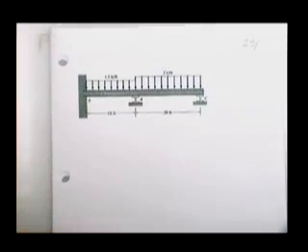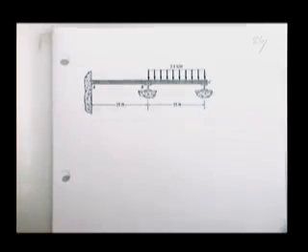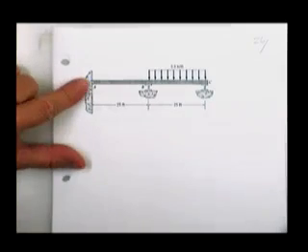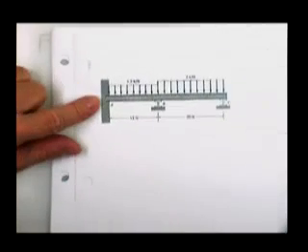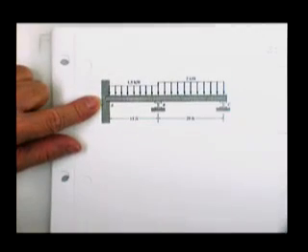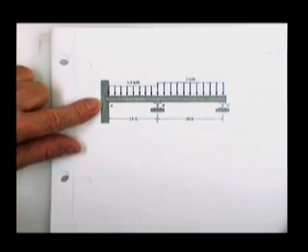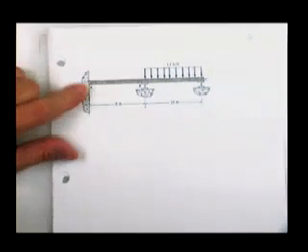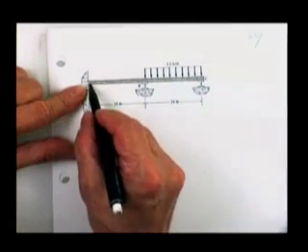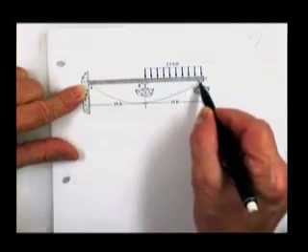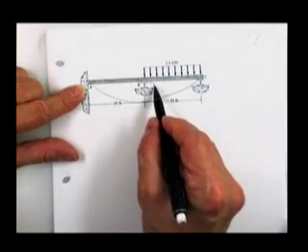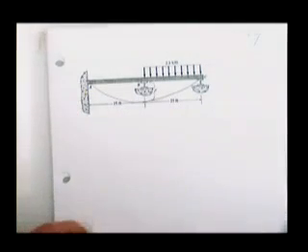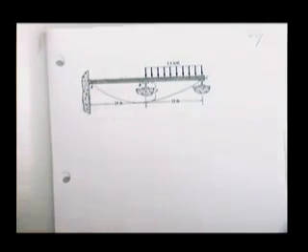Cantilever beam. Ooh, no, it's not a cantilever beam. Look at the difference. Cantilever beam jammed in the wall. Somebody spent a small fortune making that really happen. A lot of steel, a lot of welding, a lot of connecting, a lot of care, a lot of thought. So they're not easy to make in the real world. So the way they're normally done, they're just pinned. Therefore, I would consider that to be a simply supported beam. I would let this undesired thing happen, and I'd come back in and I'd get rid of it in a secondary solution.